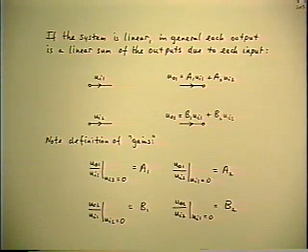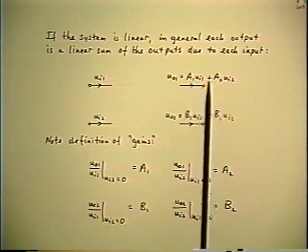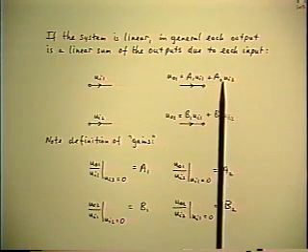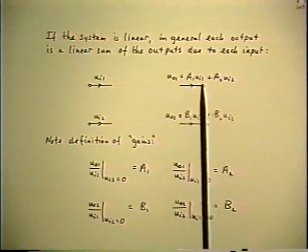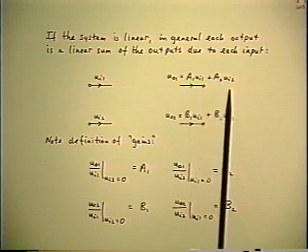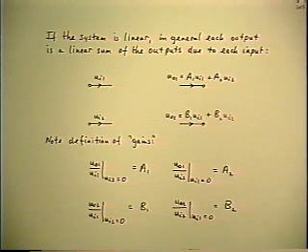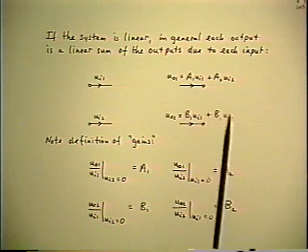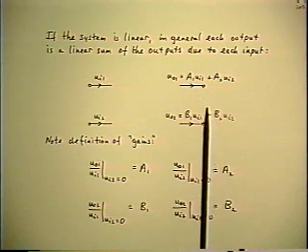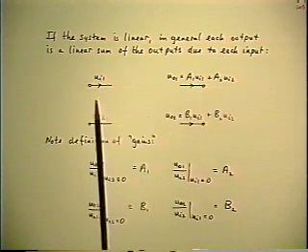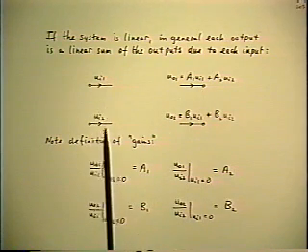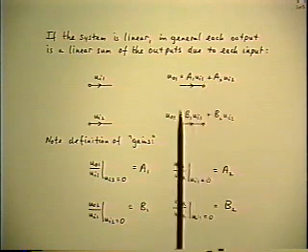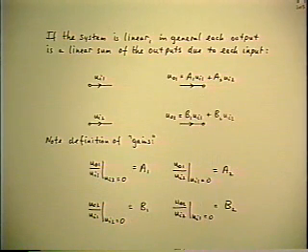Linear sum, that's all. Again, bear in mind that if these coefficients are frequency dependent, they are complex quantities or they have magnitude and phase. And when I say a linear sum, I mean a phasor sum, taking into account the phase angle. Now, this doesn't seem very interesting yet, because what it means is that according to the relative values of the 2 inputs that I'm applying, the readings of those meters can wander around and take any old values. So that doesn't appear to be useful.